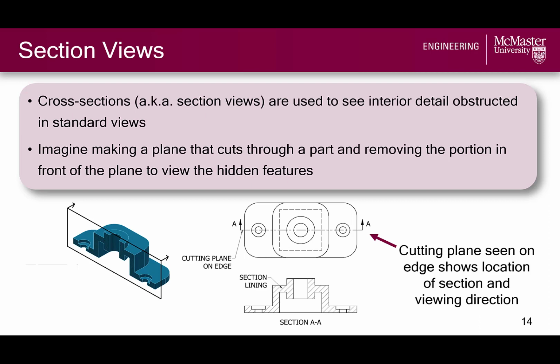In this multi-view representation, we have our standard view with the cutting plane seen on edge as a thick line with 2 dashes to show the location and viewing direction of the section view, and then we have our section view below.